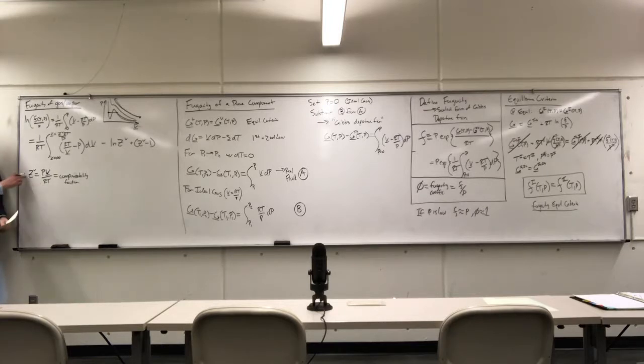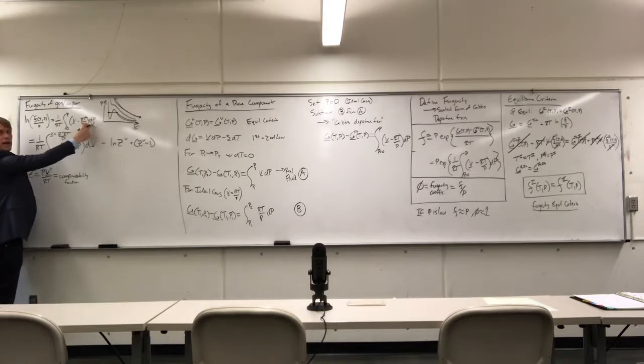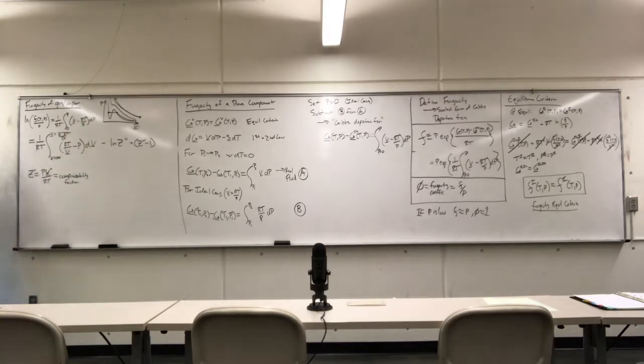We would just write Z of L, and you'd have, in this case here, the specific volume of the vapor. But you can calculate a compressibility factor for any fluid you'd like to. It's just strictly a mathematical substitution. So, the same exact concept holds true, except we've transformed ourselves out of varying units of pressure to varying units of specific volume. The easiest way to do that is to use this expression here.